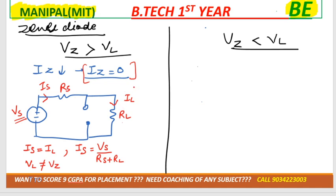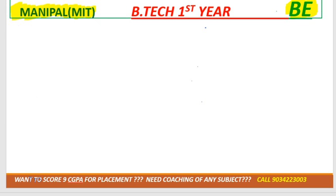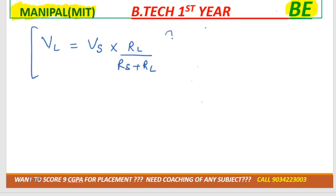Now the thing is how we can check whether we are working on the first condition or the second condition. For this you have to use one formula. The formula for VL is VL is equal to Vs into RL divided by Rs plus RL. This is the voltage division rule, that you need to study in BET. Now you will study VDR in BET, so for now I am directly telling you the formula. Okay, let me tell you the formula a little.